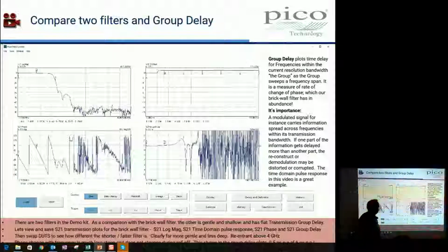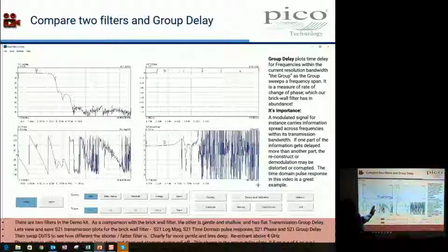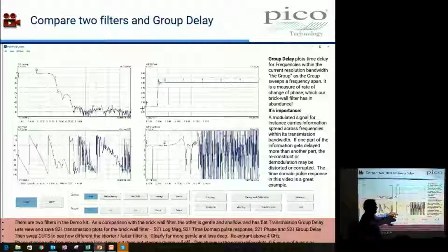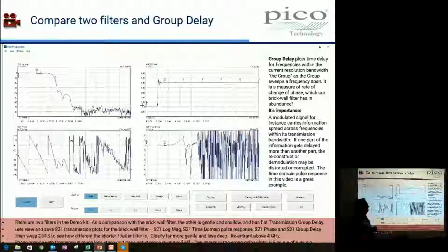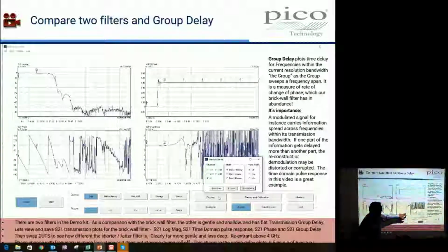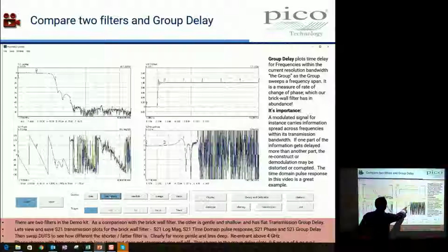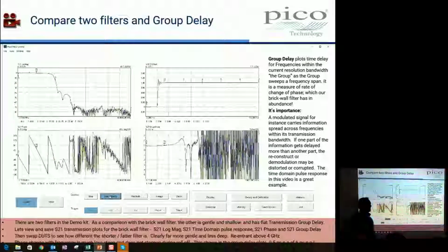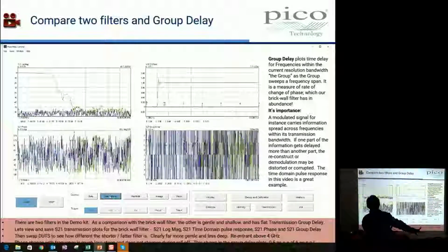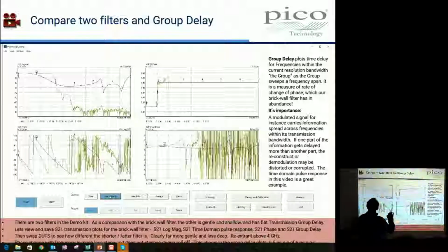We've got a group delay plot that is showing that the slope of phase is changing a lot, and we've got a nanosecond of delay overall. In this particular filter, this is not the same filter as we were using in our unknown DUT. We can see 2 nanoseconds peak there, but we can see we're getting 5 nanoseconds or so, minus 5 nanoseconds or so. In other words, this information is getting ahead of this information, and it actually does. This is real. It moves forward relative to the rest. It's not a time machine. It's not magic, but that's what it does.